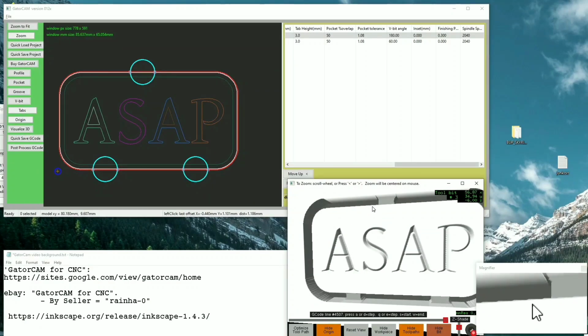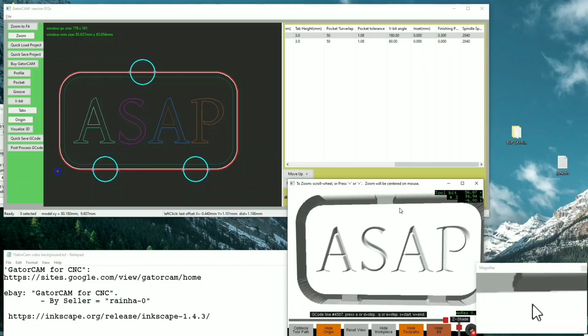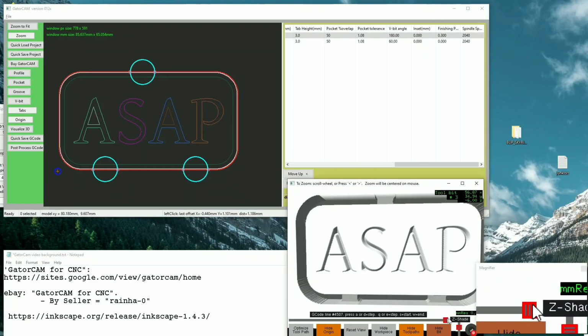And it knows automatically to step over the little tabs. It's really intelligent. It also knows to put the profile after all the other tool operations, so you don't accidentally cut something out without tabs and then try to do the middle, like this carving with the vbit. And usually it does the vbits first, I think always.